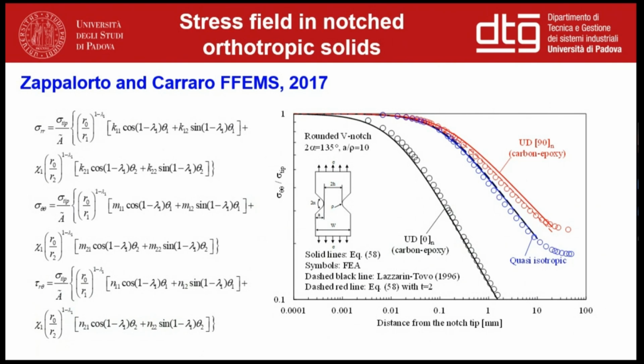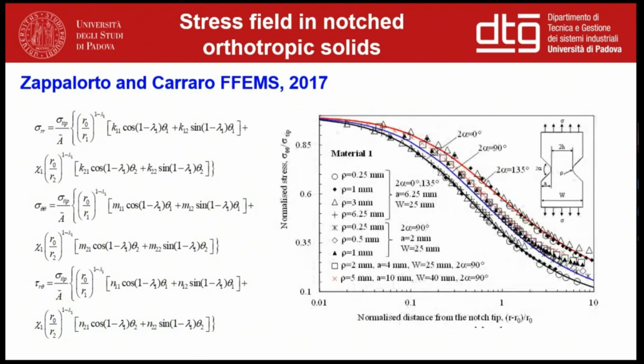And we have, some years ago, derived this set of equations in order to explain the important role played by the elastic properties in the stress distribution of notched components in orthotropic materials. In this picture, you can see also that the notch opening angle for a given material has a non-negligible effect. Indeed, increasing the notch opening angle, the stress distribution is less steep.